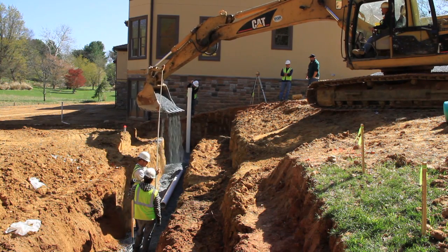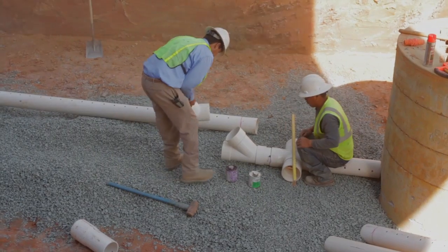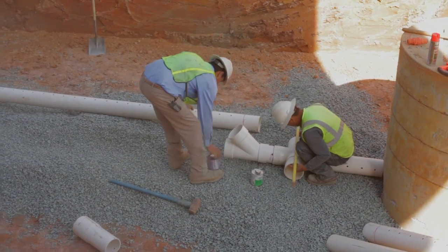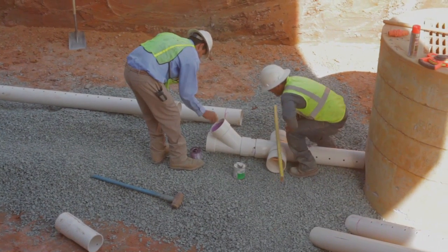These pipes need to have secure connections to prevent clogging and breakage. Additionally, cleanouts will need to be installed and angled properly to allow long-term maintenance and make certain that all segments of the pipe can be cleaned out.